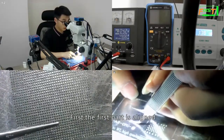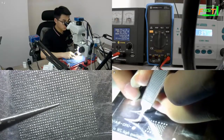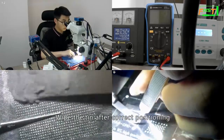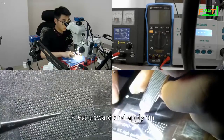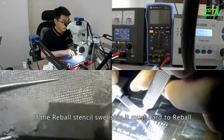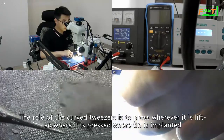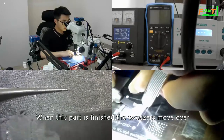First, the first part is aligned. Wipe the tin after correct positioning. Press upward and apply tin. Use tweezers, press again the lifted place. If the reball stencil swells up, it's most hard to reball. The role of the curved tweezers is to press wherever it is lifted, where it is pressed where tin is implanted. When this part is finished, the tweezers move over.